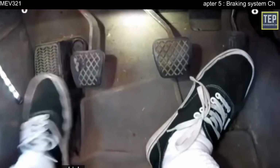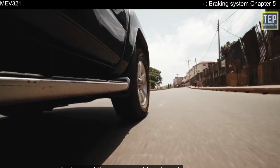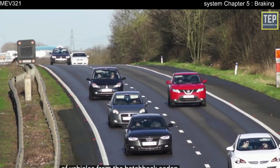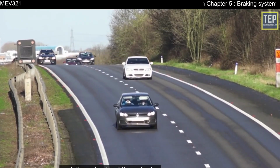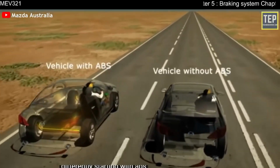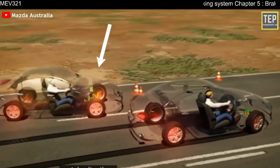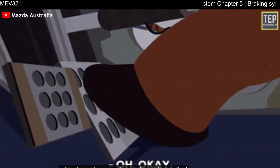Their functionality is completely different from that of the regular brakes, and these are considered much safer for the occupants. These features are present in a number of vehicles from the hatchback, sedan, compact SUV, and multi-purpose vehicle segments of the domestic market. So let's understand these topics differently, starting with ABS. As the name implies, ABS prevents the wheels of the car from locking up when the car applies the brakes suddenly in certain situations. This type of brake allows the driver to have complete control of the car's steering when maximum force is applied to the brake pedal.